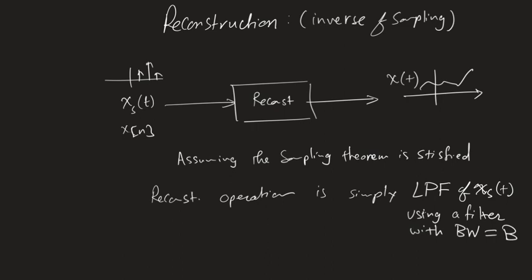So you will work with non-ideal sampling functions, and accordingly the sampled signal is going to have some non-idealities. Not only that, there is no such thing as a really finite bandwidth signal. You will deal with signals that never go to 0 in the frequency domain, so you'll have some overlapping. All of this will add some distortion to your system.